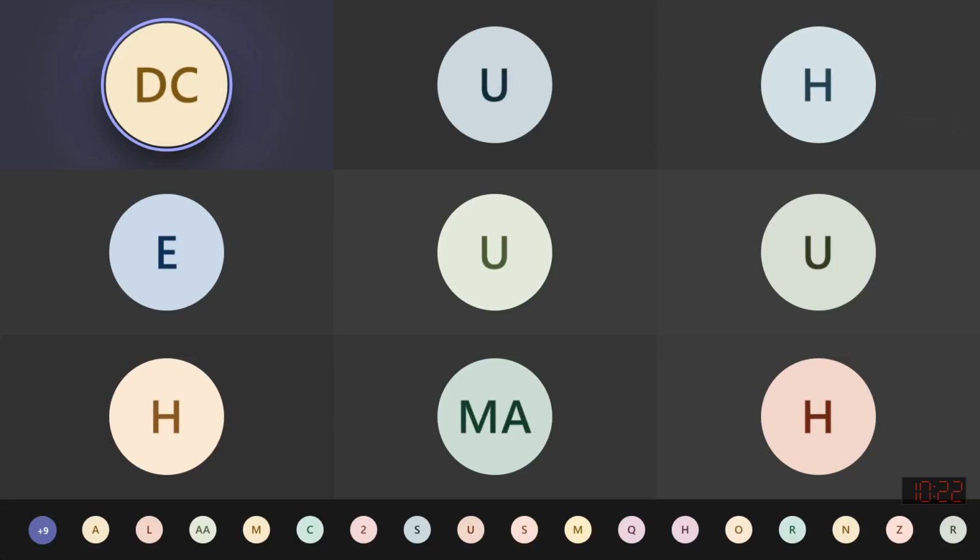You can solve the numerical easily, just on the same lines, following the unit load method, and you will apply the unit force at the location of the redundant, and accordingly you can solve it. This is the approach. Now we just try to review it.